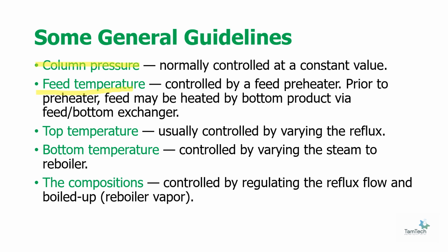Coming to the feed temperature. The feed temperature is controlled by the feed preheater. Prior to the preheater, the feed may be heated by the bottom product via a feed-bottom exchanger.